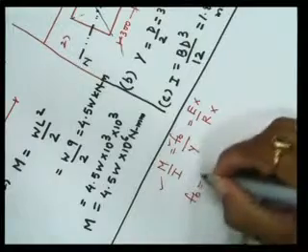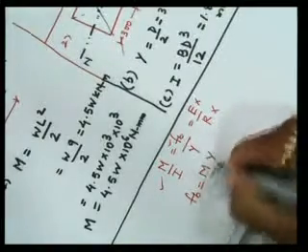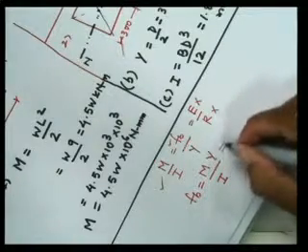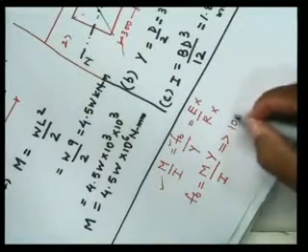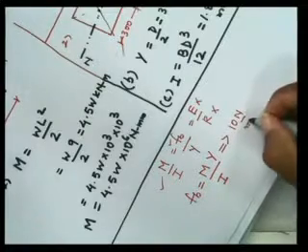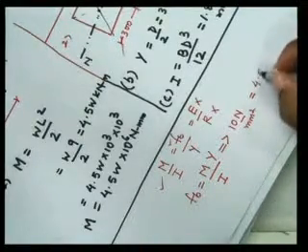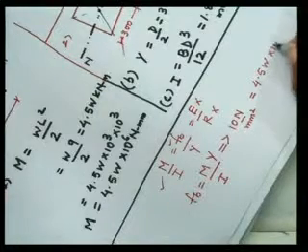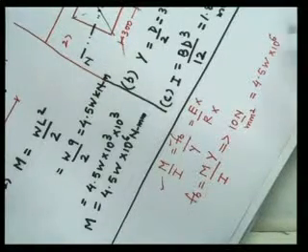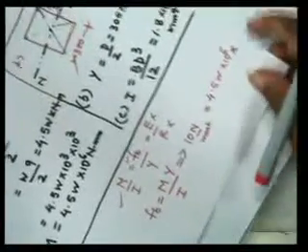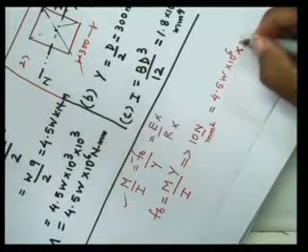Alright, so now FB, that is equal to M Y upon I. Okay, what is the value of FB they have given? 10 Newton per mm square. That is equal to M we have calculated as 4.5 W into 10 to the power 6, right, into Y we have calculated as 300.